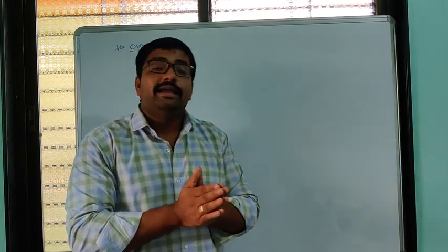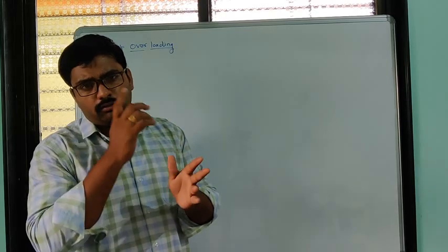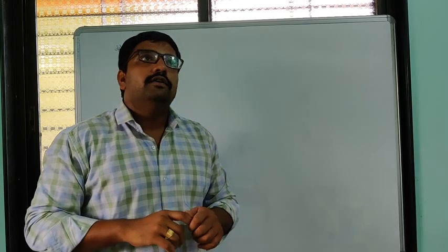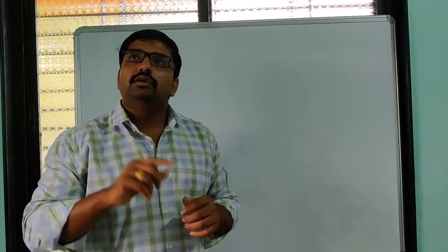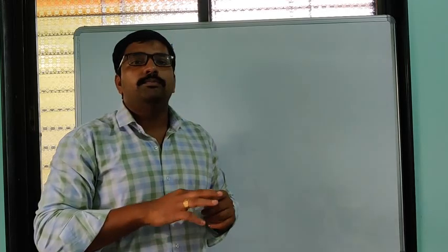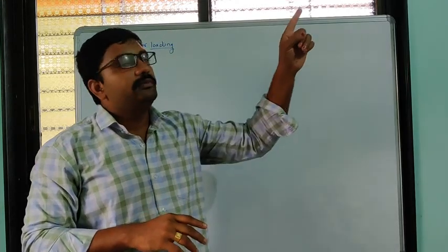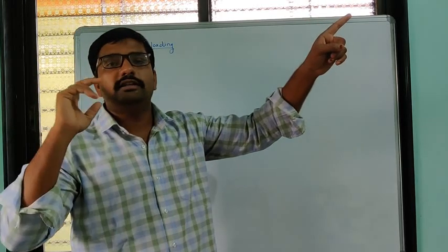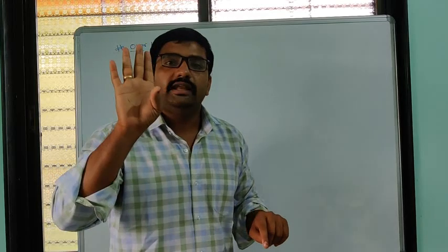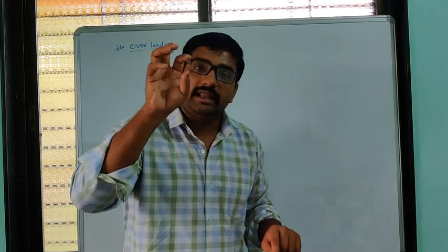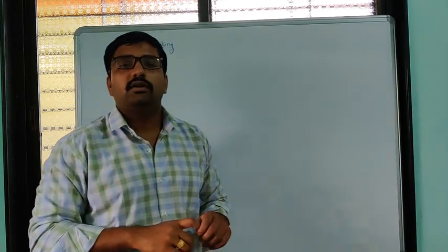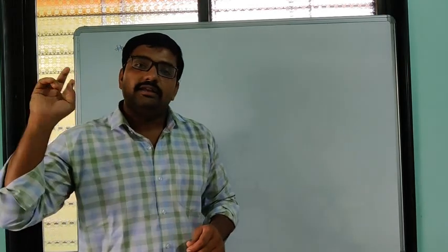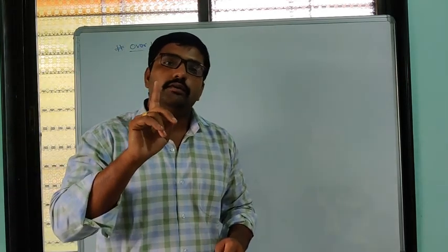Nowadays MCB boards are used. For one particular electric connection, an MCB is used. For one room, there is one MCB. So if any problem happens in this room, then the button of the MCB of that room will shut down. So the electricity of the whole home will not be affected due to these MCB electric boards. That is the advantage of MCB boards. But for the one main connection of a home, generally we have to use fuse wire.